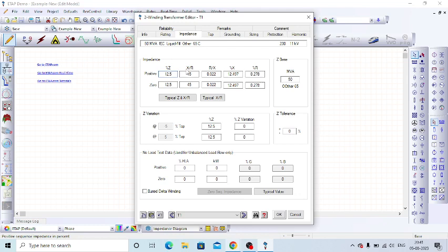So those transformers mostly will comply with any IEC or ANSI standard. In IEC, there is a requirement for tolerance. So all transformers complying with that standard have to keep the impedance within that tolerance limit. So that tolerance we will consider. The positive tolerance we have to consider for the load flow study, and the negative tolerance we have to consider for the short circuit study.